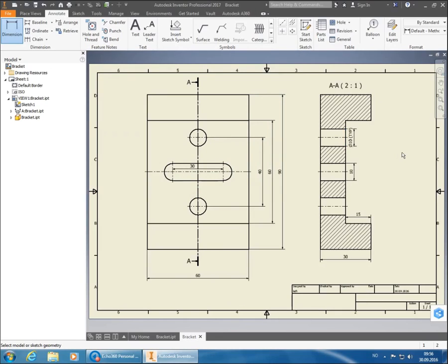And as we can see now, that becomes sort of a problem here, because we don't have enough space between our dimension lines. So we're going to just exit the dimension function completely, and then we're just going to drag the dimension so that we can get it to a different location and get it outside the dimension lines.